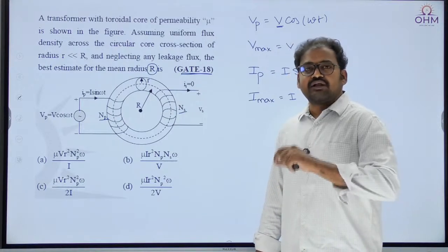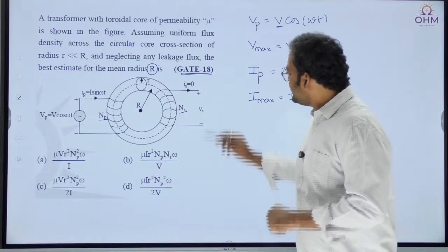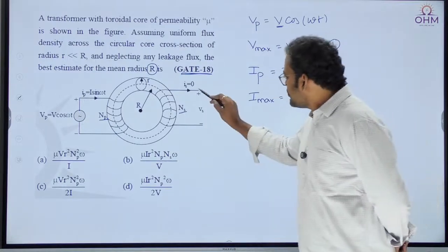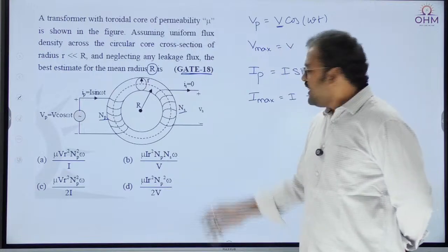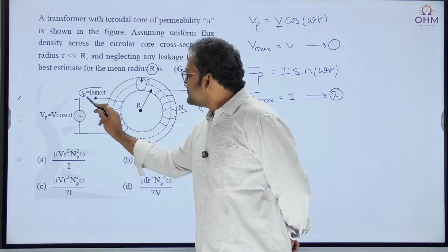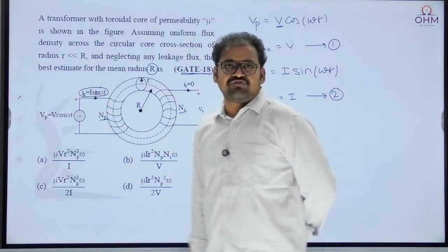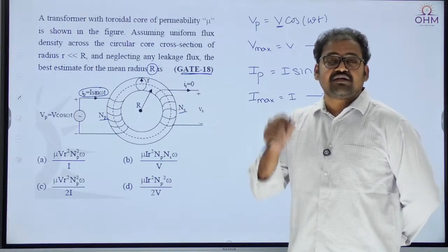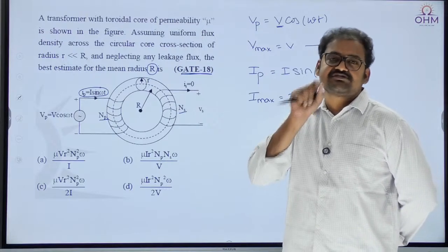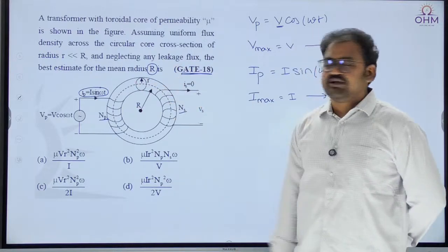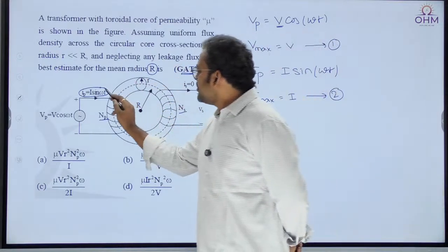Okay, so how can reluctance help us? Most important thing is, you see the secondary was connected to any load or there was no load? There was no load. As there was no load, I must say this current is nothing but magnetizing current of the transformer. Magnetizing current means it is the current responsible to create flux in the transformer core. I will talk about it also in a separate slide, but you try to understand the no load current.